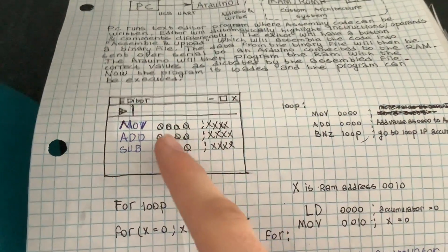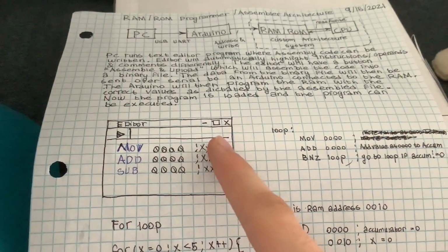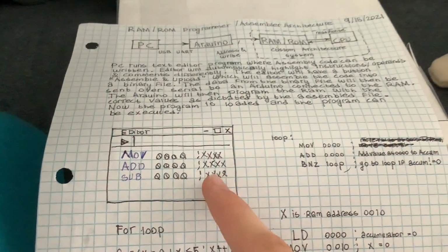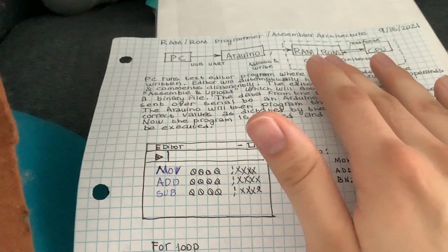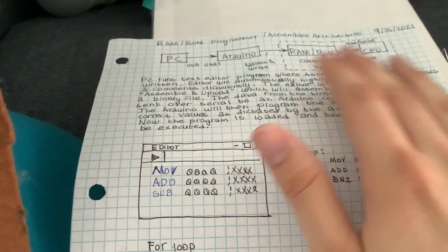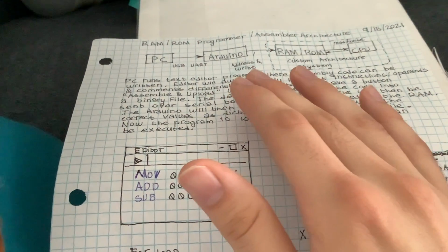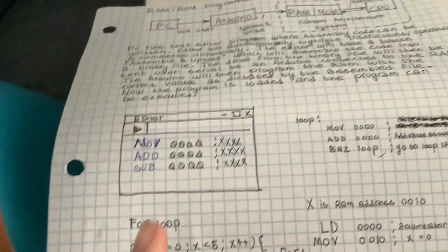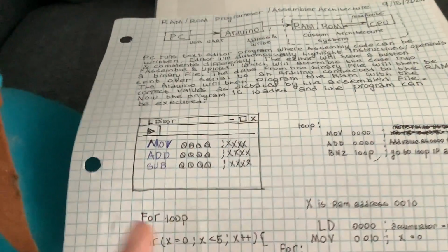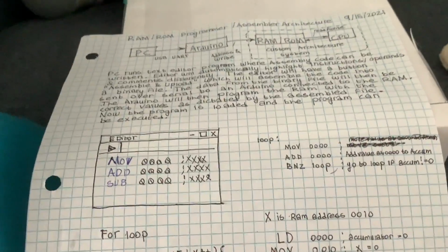And how that would work is that each of these lines is converted into 8 bits, and then each line symbolizes a different address. So this is address 0, address 1, 2, and then the Arduino will go through the addresses inside of the RAM, which is really a ROM as far as the CPU knows, and it's just going to write all of this data. So effectively what we've done is we've made a compiler, or in proper terms an assembler, and that can program the custom architecture.